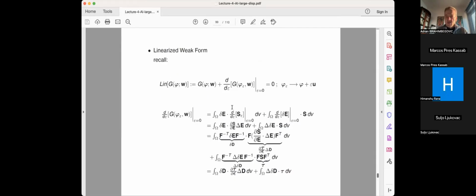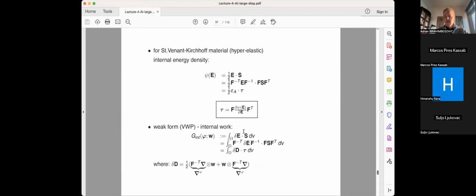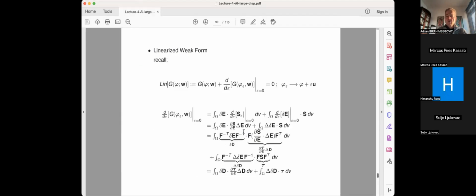So linearization of this could be, again, working out from the case that we've done for the Green-Lagrange strain, and just doing the corresponding transformation, always to recover the Kirchhoff stress from the second Piola-Kirchhoff stress. The key result is this one. And then we take the other one so you can complement, and this computation does not change the total value. You recover the results like this.